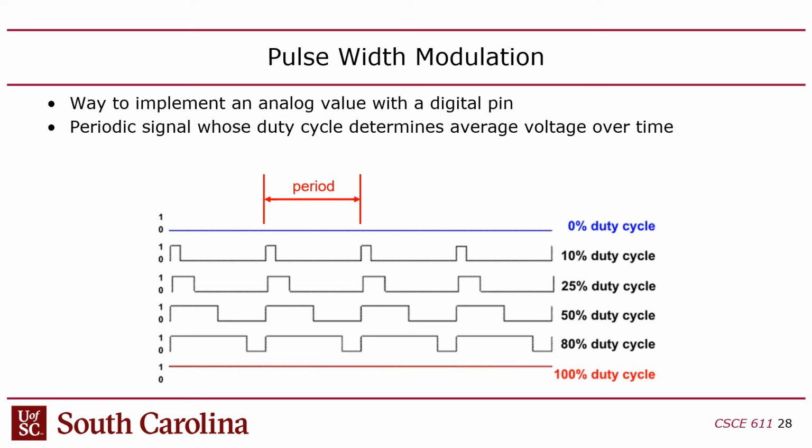Usually with embedded systems like the one that we're using in class, you'll use whatever the hardware allows, whatever it's kind of hard set up for, right? If you're designing your own PWM circuit, then you can make your own choice. In this class, we're using an FPGA that has a 50 megahertz clock, right? And so we're going to build our PWM from a 50 megahertz clock. And so we're going to have a little bit of flexibility in choosing what our frequency is.